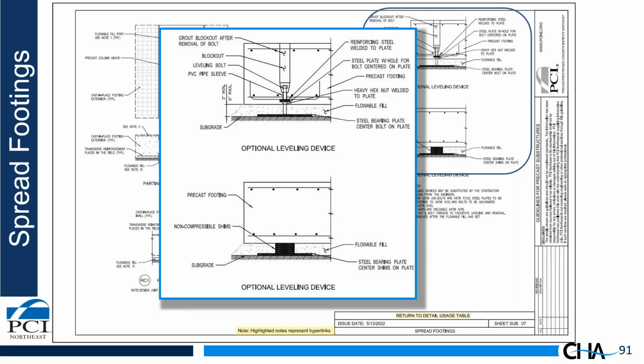You'll notice underneath these footings, the note says flowable fill. For spread footings, we do recommend flowable fill. And the reason for that is, well, I'll back up. Many people have designed these with non-shrink grout between the footing and the soil, or the subgrade. The reality is the soil pressures on the bottom of typical footings is in the range of 100 to 200 PSI. So we don't need a 5,000 PSI grout to take that force. Flowable fills typically have strengths in the order of 1,000 to 2,000 PSI, and it's perfectly adequate for spread footings.